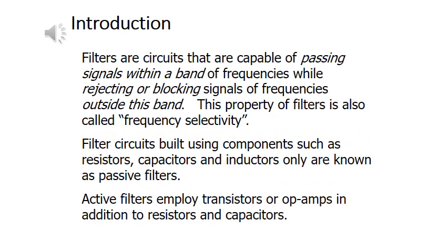Filters are electronic circuits that are designed to select or reject a certain set of frequencies or certain single frequencies as well. There are two types of filters that we generally use in our applications. One is the passive filter and the other is the active filter. The filters that are comprised of basic components like capacitors, resistors and inductors are passive filters. Passive filters are designed to eliminate or extract, select or reject a certain single frequency.